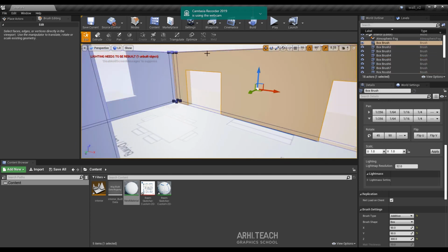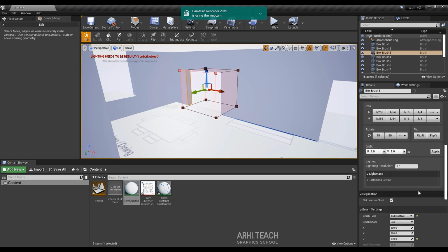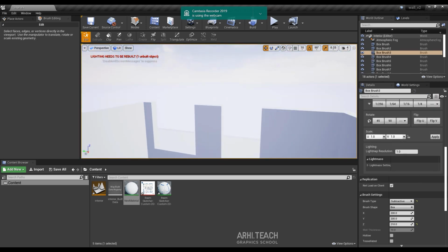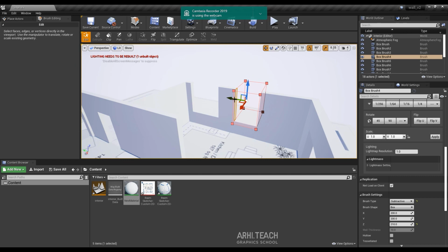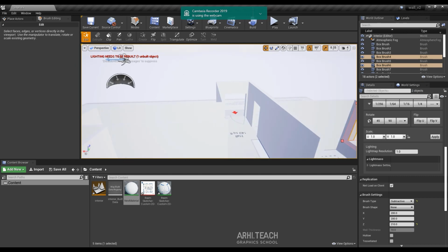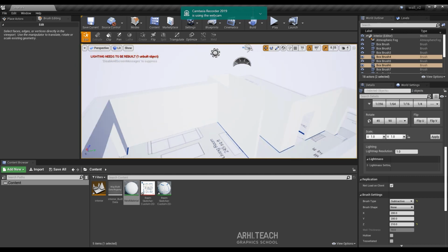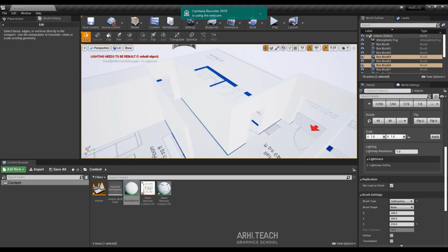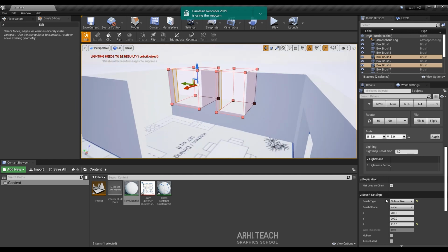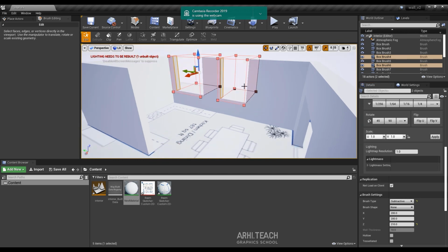And when we copied and pasted these boxes to our windows, its height also remained 2100. So we select windows. That's all actually, 2 boxes. And here set height to 1200. No, not this one. No, it's correct actually. This value should be 1200. Yes, it's correct.